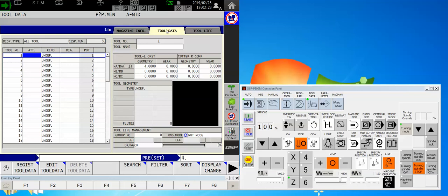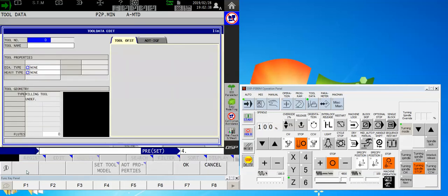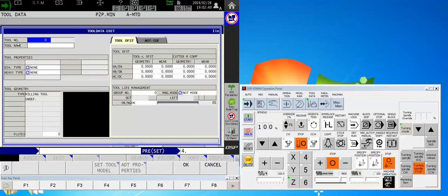So in order to populate the Tool Data tab, bring the tool from graphics to the Tool Data tab, I go into my Tool Data mode on the machine, touch the Tool Data tab, and now I'll simply register the tool data. The first question to bring up is, what is this tool number?